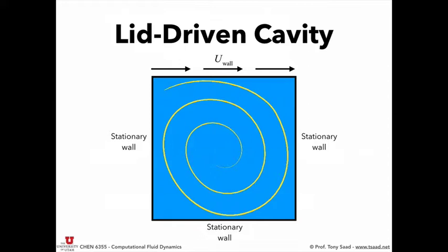Anyway, so this is Z. There are vehicles driving here, et cetera. He wants to study if there's a pollutant here that's being blown, what happens to the pollutant as you get close to the street? The idea here is you treat this as a cavity with an imposed velocity at the top. Okay? That's the meaning of the lid-driven cavity problem. It is a legitimate problem.